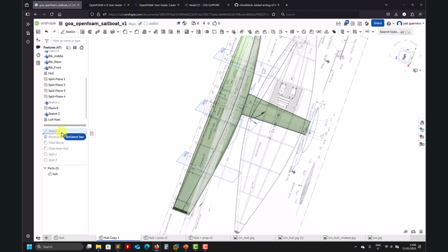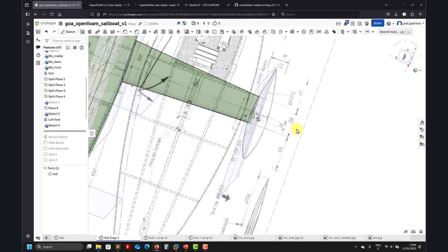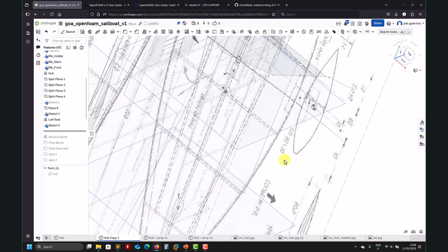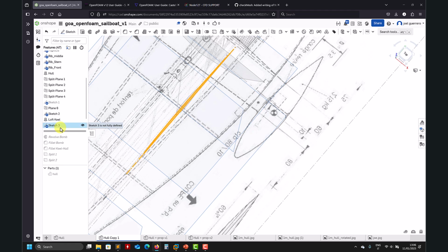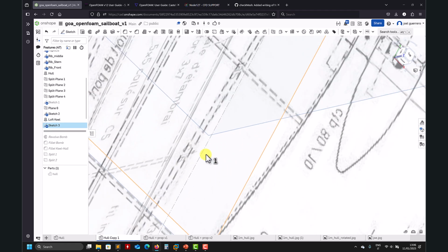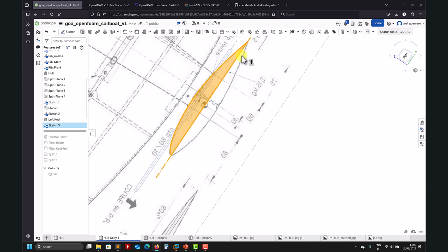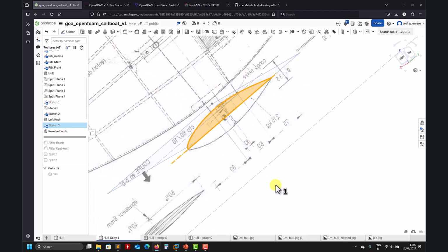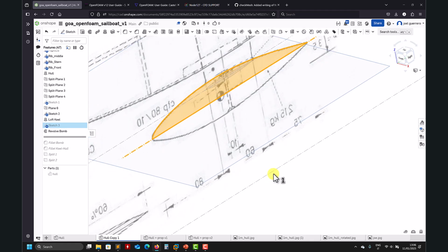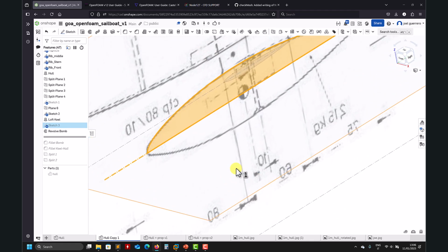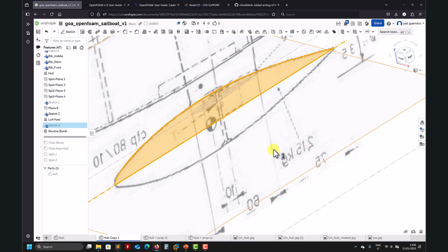You have the keel there. And you can get an idea that everything's like that. So now we have the hull here. This is a little bit tricky in the sense that this is not tricky for meshing. I don't want to go into details of the kind of geometry, but see that I create just the cross section and then it's a revolve. But usually this surface of revolution, you will see when you save the STL and you open it, they're very particular. You have singularity, singular points, and sometimes they can give you problems from the geometrical point of view, but it's not a big issue, but you should be aware of that. So basically, it's a revolve.